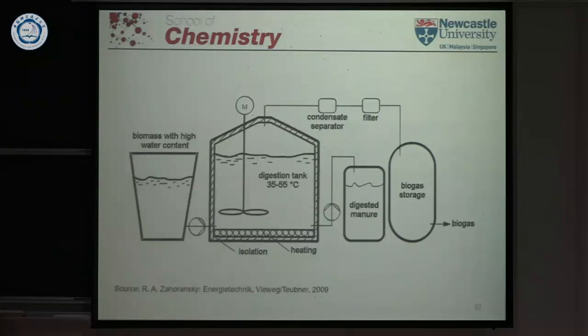And biogas can be used for burning. There have been attempts also to use this in conjunction with fuel cells, specifically with high temperature fuel cells, SOFC, because the chances of using such gases with an SOFC are much better than with a PEM. With a PEM, at the low temperature, you very easily get some contamination effects from the carbon monoxide with the platinum catalyst.